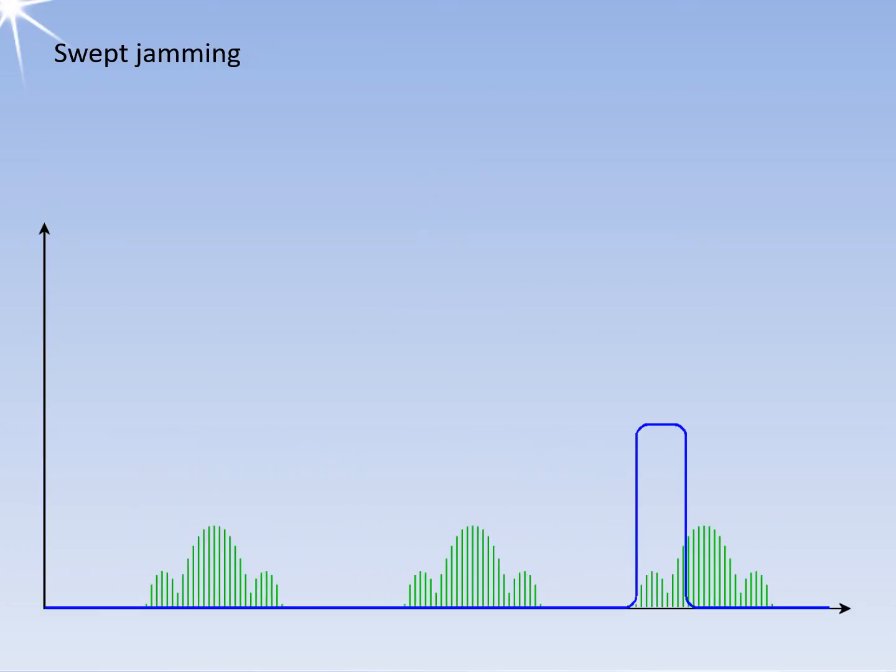Swept jamming is a kind of spot jamming in which a narrow frequency band of jamming energy is repeatedly swept over a relatively wide frequency band. The sweep rate is such as to be on any given frequency only long enough to accomplish its jamming task, returning to that frequency again before the expiration of the jammed circuit recovery time. Sweep jamming combines the advantages of both spot and barrage jamming by the rapid electronic sweeping of a narrow band of jamming signals over a broad frequency spectrum. The disadvantage of sweep jamming is its high susceptibility to electronic protective measures.